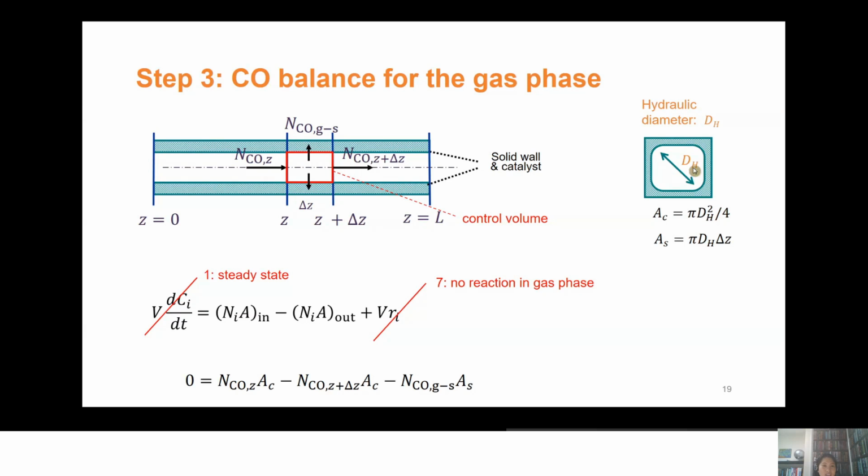So we can just now use a circular cross section to describe our channel, using the hydraulic diameter to give the same behavior as the non-circular channel. So the cross sectional area AC is therefore just pi dh squared over 4. Agree? This is the one that is normal to the axial flow. So using the hydraulic diameter, we can just assume that this is circular.